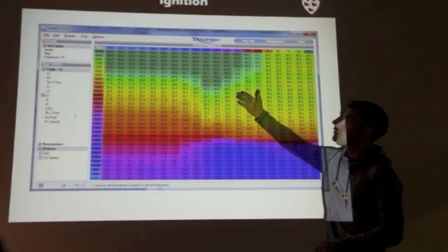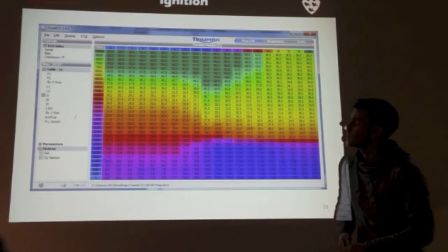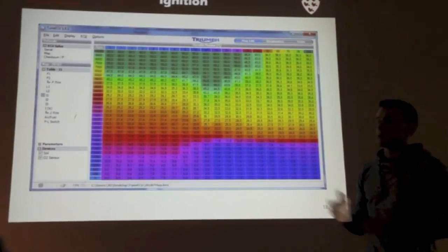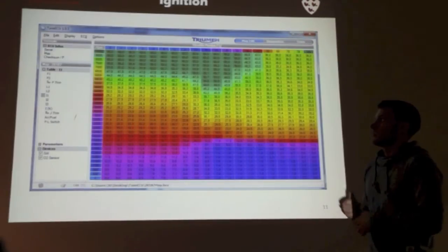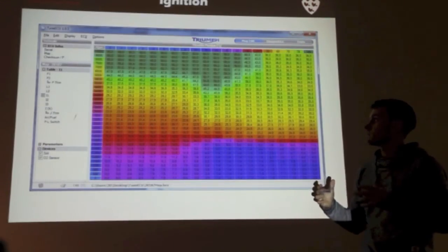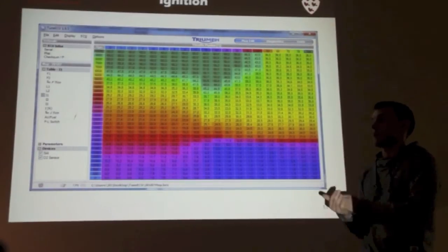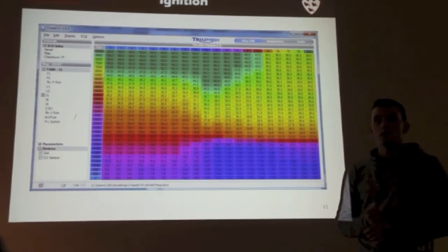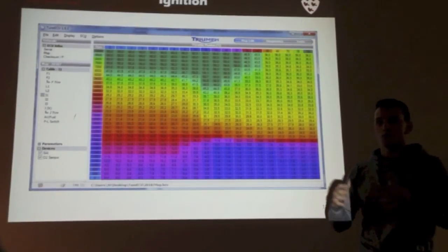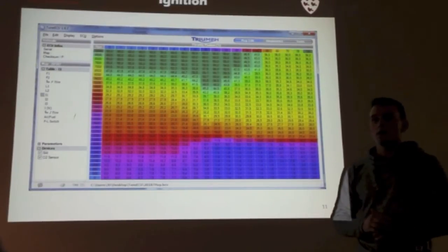And then as RPM increases, you see it increases all the way up to a maximum of 60 degrees there. And that's important because, in the ideal world, you'd want to advance your timing as little as possible, because that reduces the amount of negative work your engine is doing.